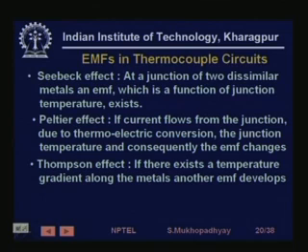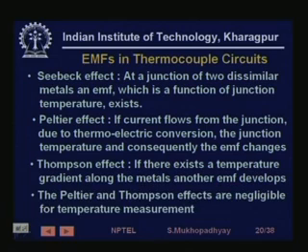Similarly, you have the Thomson effect, which comes into play if there exists a temperature gradient along the metals. Then you have another EMF developing, but this is also not so important. So for temperature measurement, the Seebeck effect is the main effect we are going to look at.